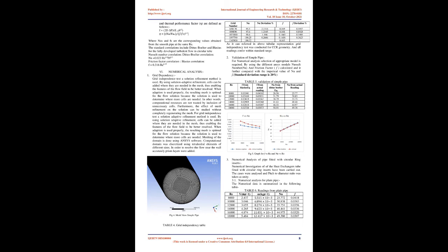A 3D geometry is created by using ANSYS Workbench. Proximity and curvature sizing is used for meshing the geometry. It is meshed as shown in the figures below. Total number of nodes used was 607,409 and total number of elements used 1,660,258. Fig 3. Mesh body sectional view.